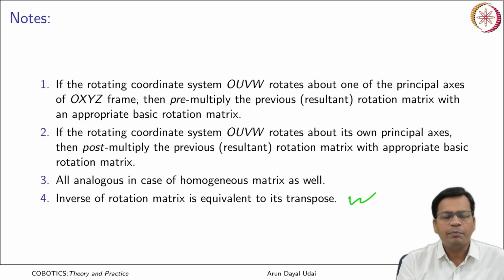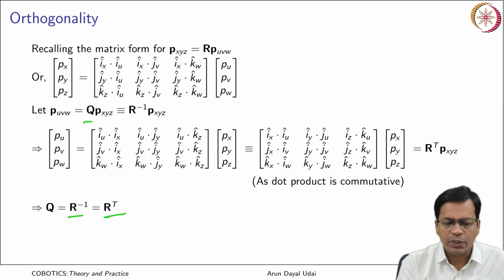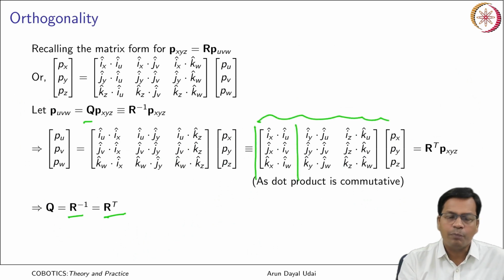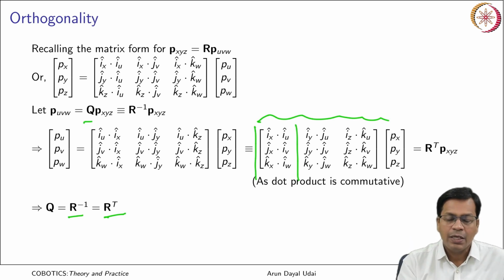There are still many other rules that you can notice while we discussed the rotation matrix. Coming back to that, let us say you just take any rotation matrix. All these elements are basically components of the same vector along x, along y, along z, and that vector was a unit vector. So, each of these columns represents a unit vector.